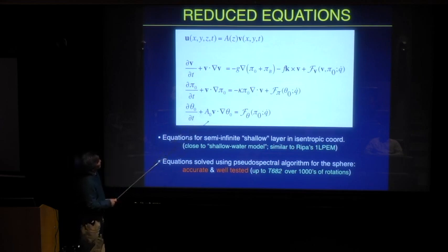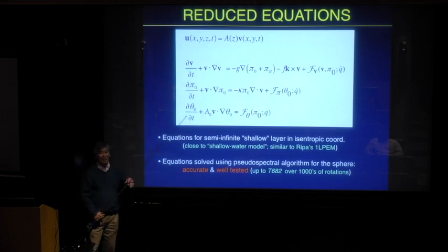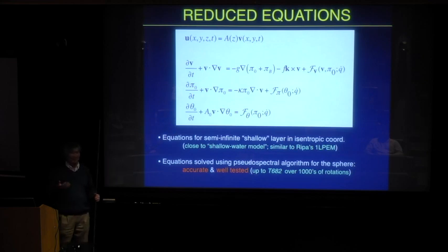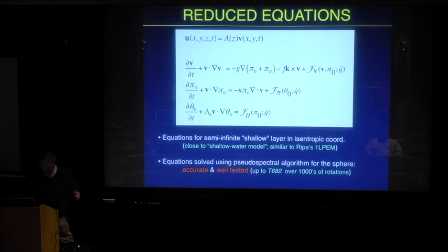If you set A naught equal to 1 and let kappa go to 1, then it reduces to your shallow water equation. Okay? I particularly like it because there's a huge set of machinery already available to solve the shallow water equations, and solving this set of equations using those tools is fairly simple.